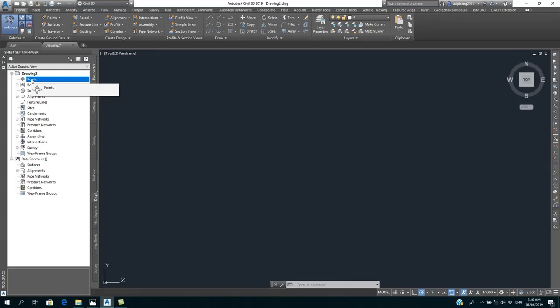At the end of it, I have the surface of the design levels and the existing, and I export it to Infraworks. We explain the procedure, and at the same time, I can work from the preliminary point of view from Infraworks directly. It means that I can use the location of the environment I have in Infraworks to coordinate a preliminary design on that site for a quick review of the horizontal and the vertical profile.